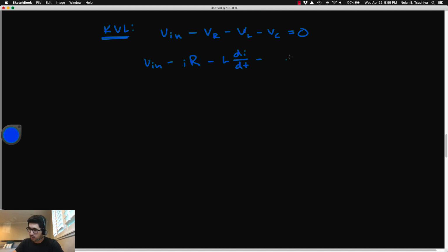Okay, so dealing with essentially solving for the voltage in that capacitance rule, we get 1 over C times the integral of I dt, or d tau. Okay, so this is basically for all time prior. It looks a bit messy right now, but this is a symbolic representation of the voltage across a capacitor. Okay, and this was derived just by taking the integral of both sides of the capacitance law. All of this should equal 0. We'll call this equation A.